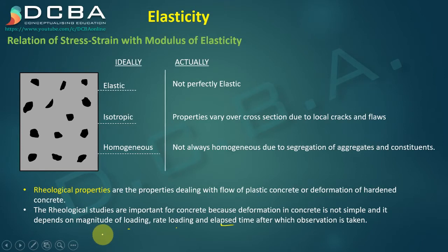So regarding rate of loading, you should understand that when we perform tests in the laboratory, the rate of loading is gradual. We vary from 0 to a particular load, and then we plot the stress strain curve. But there are times when there are loadings like impact loading, when the load suddenly rises, or even blast load, because of the blast that takes place at a certain point, the sound waves that hit the concrete are very sudden. So such kinds of loadings will have a higher rate of loading.